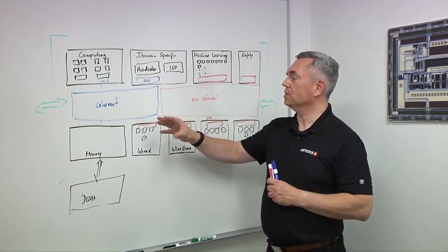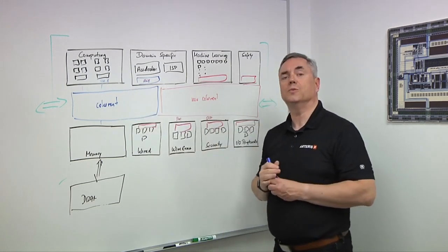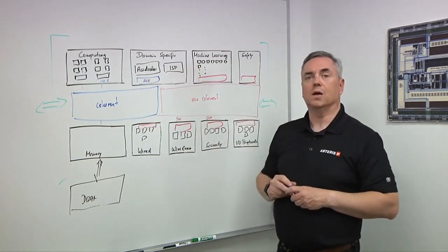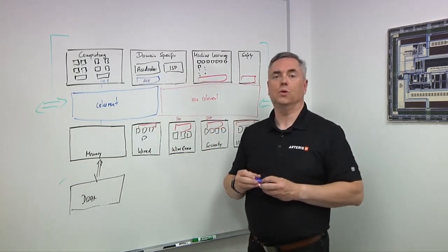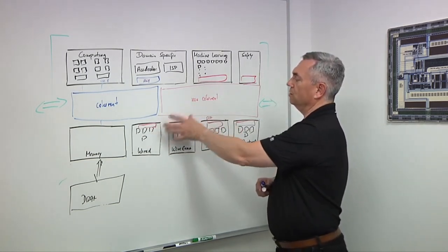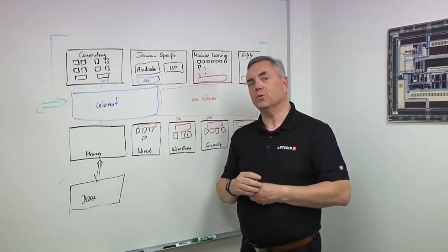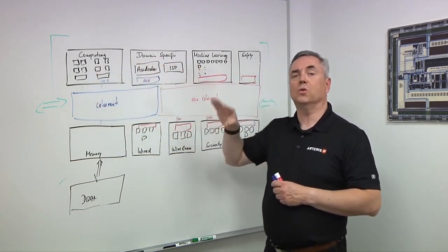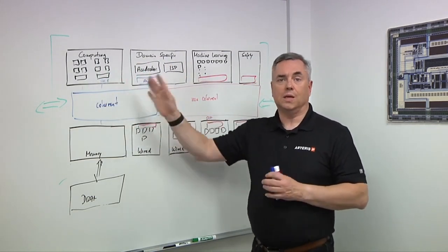So one of the challenges is how do you bring them all together for the coherent and non-coherent bits of the chip? And so, how do you do that? Because that is one of the big challenges. We, as a NOC company, a network on chip company, have all these protocols learned, if you will. We have specific interfaces for our NOC, which takes the different interfaces and unifies the protocol salad and allows you to combine everything, both in a coherent and in a non-coherent fashion, and then have an internal protocol that carries all that along and translates it for it.